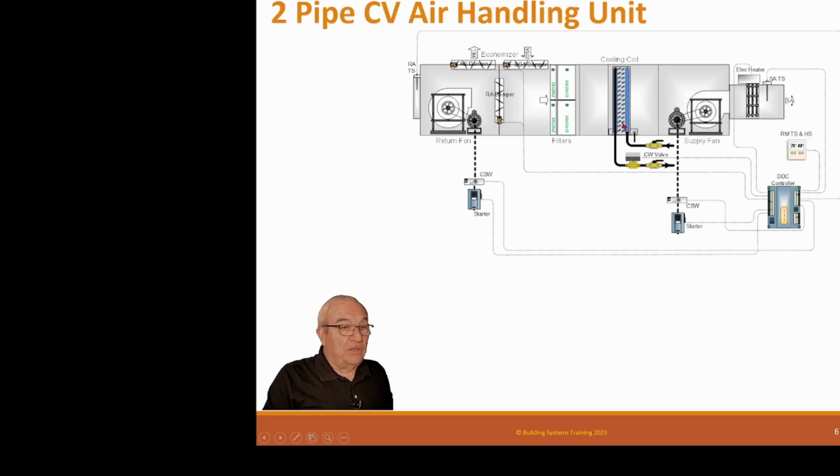That's really, really important. If you do it the other way around, where you have the coldest water coming in over here, then when the air leaves this coil, it's going to be at the return water temperature, which could be 65, 70 degrees. It could be warmer. And the problem is that doesn't allow the cooling coil to properly dehumidify the air. It doesn't take the moisture out of the air. So you'll get higher temps in the space and problems. So they always must be leaving. A supply needs to enter on the leaving side of the coil.